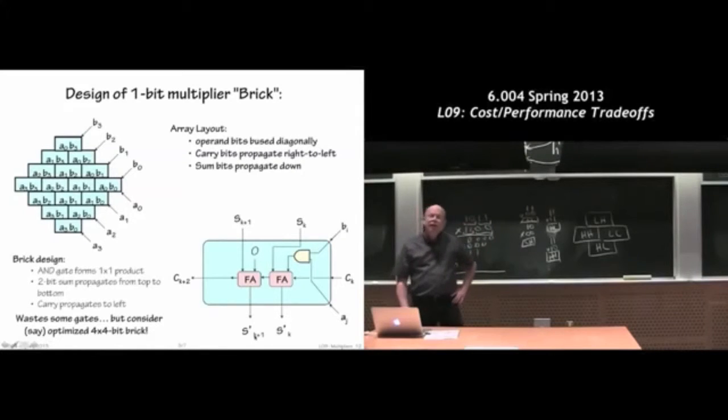And here's a little piece of circuitry involving the full adder building block. It adds together 2 bits and a carry in, so 3 incoming bits, and produces a sum and a carry out. Okay, so this is our little building block, like so. This is really the only thing where you actually have to do circuit design. And now we're just going to figure out how to piece these building blocks together to form the actual resulting multiplier. This is not the most efficient thing.